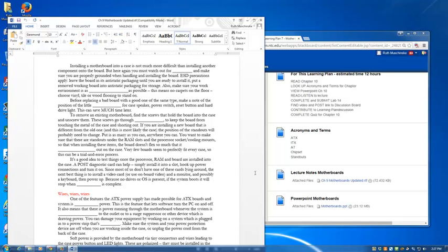Also, make sure your work environment is as static-free as possible. This means don't work on a carpeted floor. Choose vinyl, tile, or wood flooring to stand on. In fact, there is something to be said for using your kitchen counter as the place to do your computer assembly. Usually, there are no carpeted floors. Static is at a minimum.